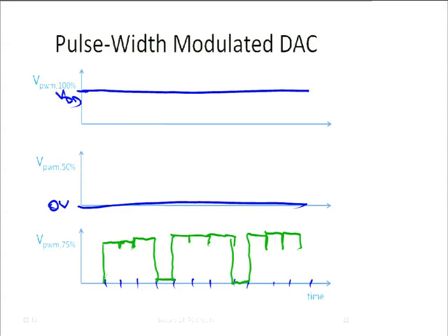Right? So what would happen? Well, the output is now high 3 times and it's low 1 time. If for example, we were to control a light with that, how would the light look like? It would look dimmed, right? Because it is not on all the time, so we're not getting as much light. Well, if we do this very slowly, the light also would flicker. But if we were to do it fast, to our eyes, it would look like it is dimmed, right? And how fast would we have to go if we were to use this for a light?